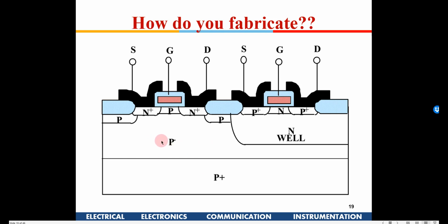So this is what today's technology has: an epitaxial P out here, and then you have this N. This is the channel region, so you have a gate here, and for a PMOS you have an N well here, then you have P+ being doped here, so the channel remains N, and then you have a gate connection, source and drain connections. Okay, so this is what our final chip is.